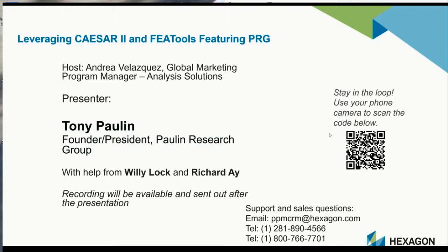Okay, great. Is it possible to customize the shoe design wizard based on custom supports? Willie, can you answer that? Yes, you can. The custom supports will have to be built in NozzlePro, and those can be used for analysis type in the pipe shoe design wizard. So we would compare the restraining loads from the Caesar model against the allowable loads built from the NozzlePro model that's custom. Okay, great. We do have some customers that build their own libraries of pipe supports. When they have specialty pipe supports, different allowables, different wall thicknesses, they can design them any way they want. And then when they go to select pipe shoes, they can select from their own personal library.